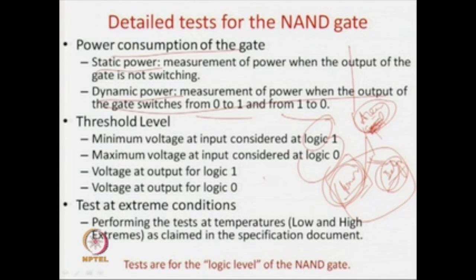Generally, we can say that in some kind of circuit where 5 volts is considered the upper threshold and 0 volts the lower threshold, anything above about 4.8 volts, up to say 5.2 volts, we call logic 1. And logic 0 we can say is when the voltage is up to about 0.3 volts. So, in this specification, if I get something at 0.3 volts or below, I call it logic 0, and from 4.8 volts to 5.2 volts I consider it logic 1.